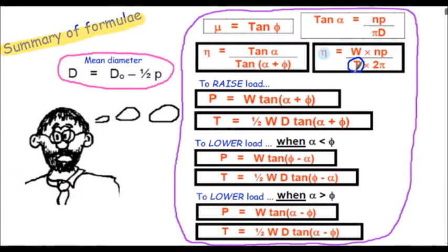So knowing the overall torque, you can subtract from that the friction, and that will then provide you with the value of the torque required to overcome thread friction. From there you can use this equation, and knowing friction angle phi, you can then calculate the friction coefficient mu. So I'm not sure if those hints help you with your solution development, but I would encourage you to stop the presentation and attempt exercise 3, although the full work solution is shown on the following slides.